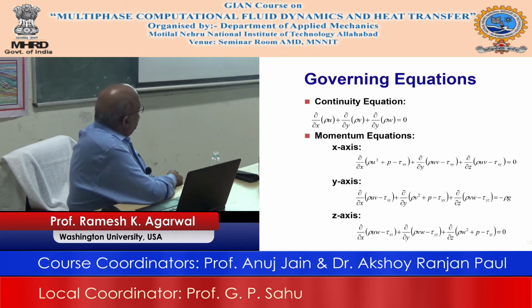So that is what you do, and now the effect of the free convection comes in here, and that is a Boussinesq approximation to approximate what? The buoyancy force. The buoyancy force is proportional to the temperature difference, and that is the Boussinesq approximation. And so that is given here, and then of course the rest of the equations are the same.